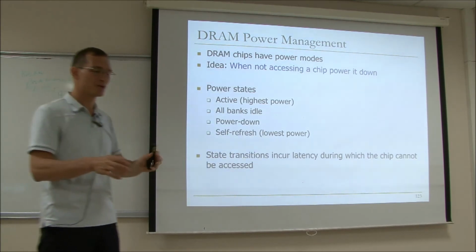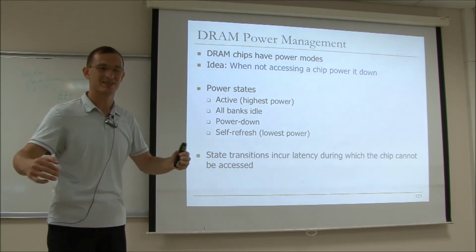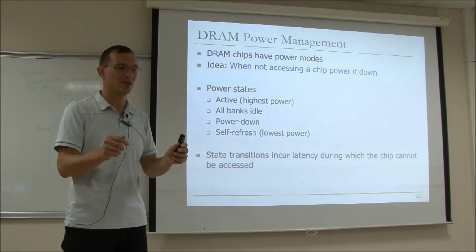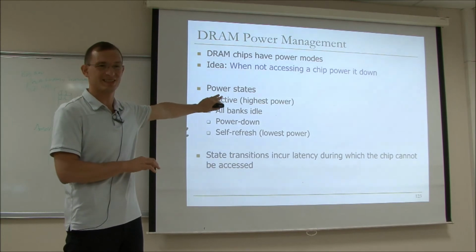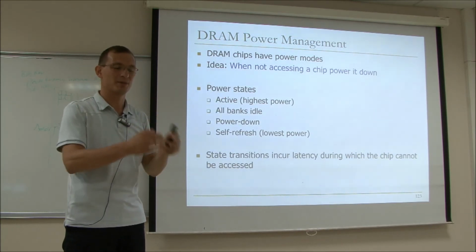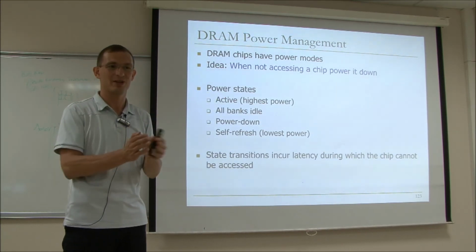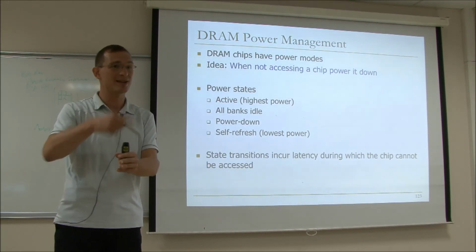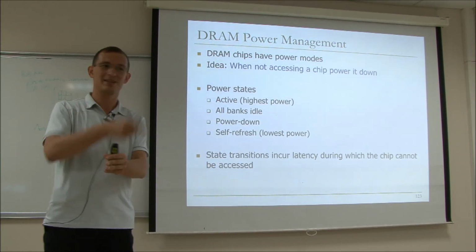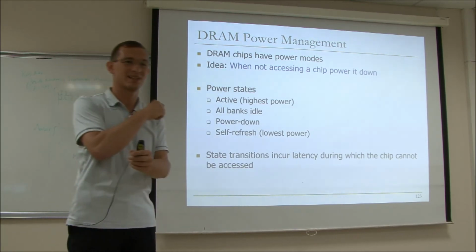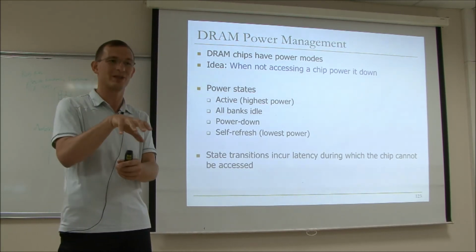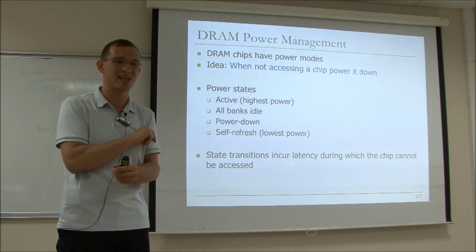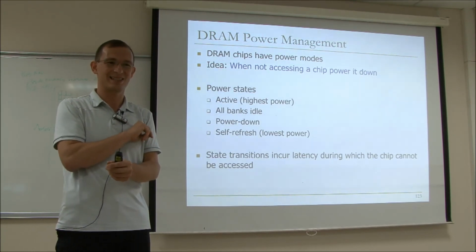But people have proposed actually adding more row buffers. So the row buffer is really needed because it's a sense amplifier. But people have proposed cached DRAM, where you add more SRAM cells to buffer rows, and then you can manage the cache that way. And I'll talk about those a little bit when we introduce some other way of using part of the cache as part of DRAM as cache. We'll get to that, I think.